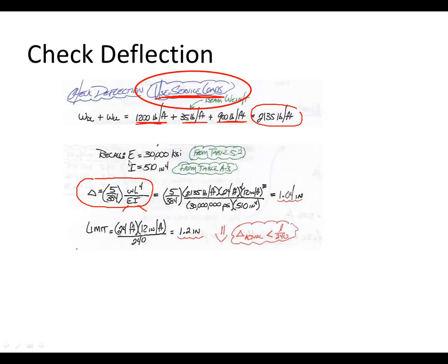And so modulus of elasticity for steel, if we pull that from table 5.2 in your textbook, table 5.2 lists this as 30,000 KSI. Occasionally you'll see some tables will have this as 29,000 KSI. I believe your textbook shows A36 still as 29, and they increase it to 30,000 for 50 KSI steel. You go ahead and use whatever's in the table there. It doesn't change the number by that much. You use the 30,000 KSI that you pull from the table.